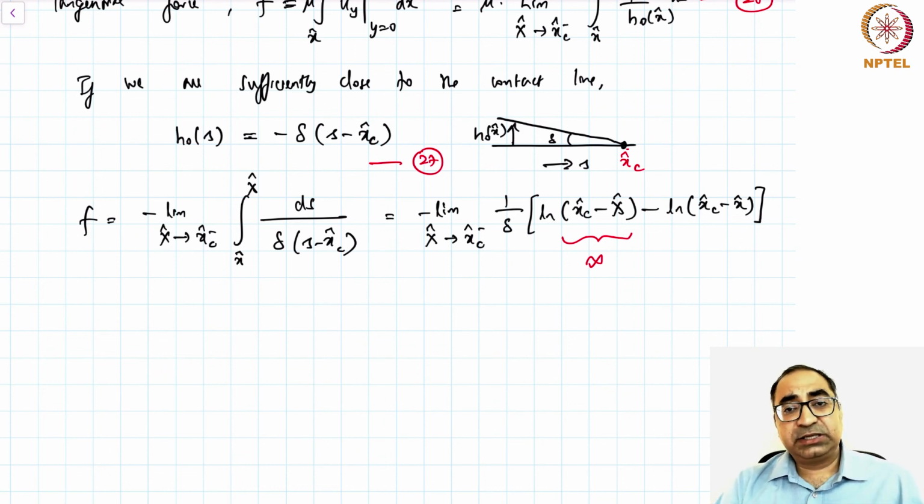There is another suggestion that the no-slip boundary condition is the culprit. Therefore, perhaps the no-slip boundary condition itself is not valid. There is also evidence to say that the no-slip boundary condition is not valid. If you look at a more kinetic theory based approach, then you can come up with an expression for the effective slip length, meaning the length scale over which the fluid actually slips over the solid. The no-slip boundary condition is not strictly valid. There are other suggestions as well.